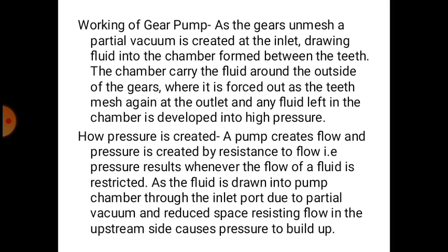How is pressure created? A pump creates flow, and pressure is created by resistance to flow. That is, pressure results whenever the flow of the fluid is restricted. As the fluid is drawn into the pump chamber through the inlet port due to partial vacuum, and the space reduces, resisting flow on the upstream side causes pressure to build up.